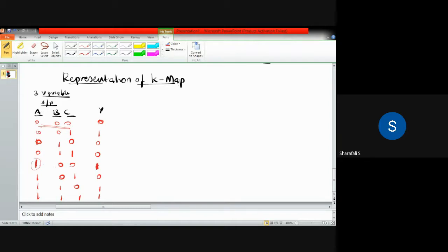Some logical operations are happening inside that circuit, and we are getting outputs like this as well. Now, using a truth table like this, we can also represent these outputs in that particular K-map. If you consider this case, we are having three variables here.